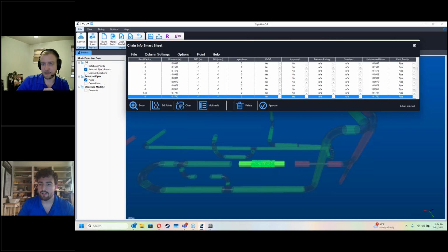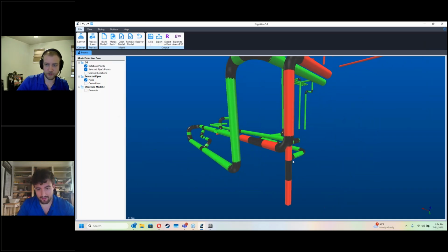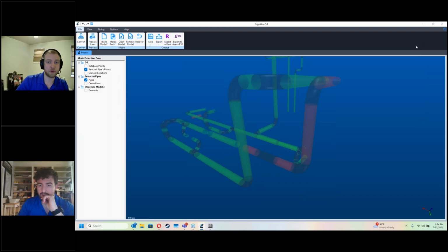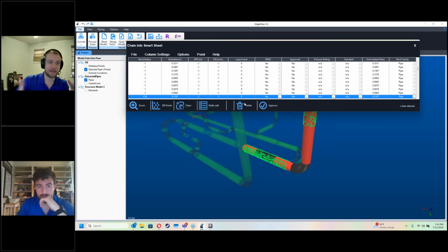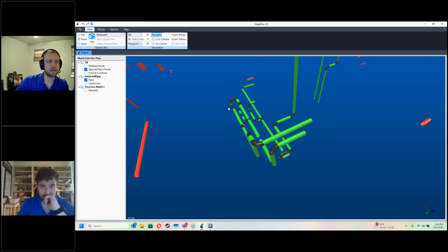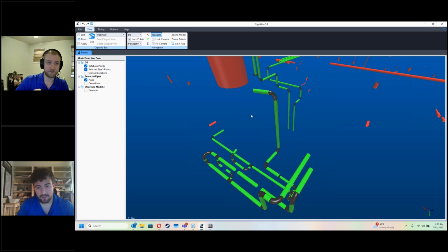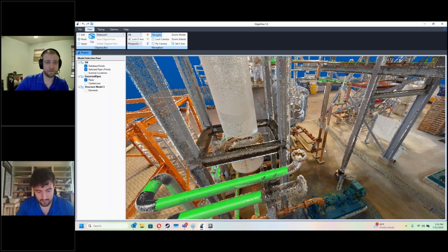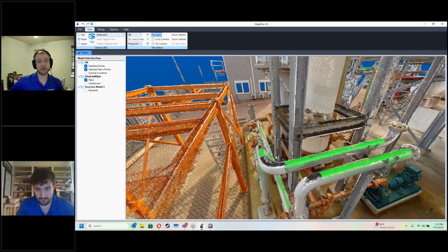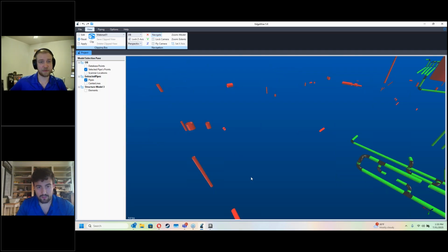Let's see. So just another question on European Revit families. We're just dumping generic objects into Revit from EdgeWise. Once they're in as generic pipes, you can switch them with whatever family your project works with. The thing we'll point out is that the legacy Revit plugin that comes with EdgeWise has some limitations on international versions of Revit. If you're using different languages of Revit, the legacy plugin that comes with EdgeWise is a little bit limited. It can be tricky for that.